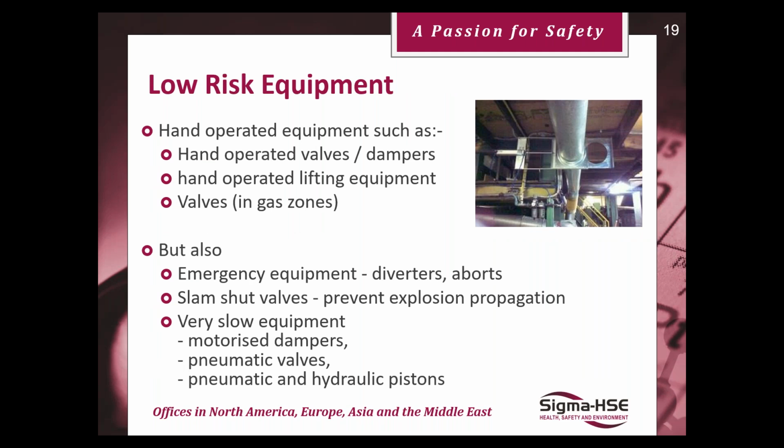So the same methodology can be applied to valves, maybe damper valves, maybe just simple, relatively simple equipment like pneumatic valves. I guess this is where it mentions pneumatic valves. This is much more to do with vapor environments. Usually in dust environments, you can get away with it, if it's legacy, if it has ingress protection. So it's easier to protect against dust ingress. Whereas if it's vapor environments, they have their own level of sealing protection that you need. So it's something to consider.